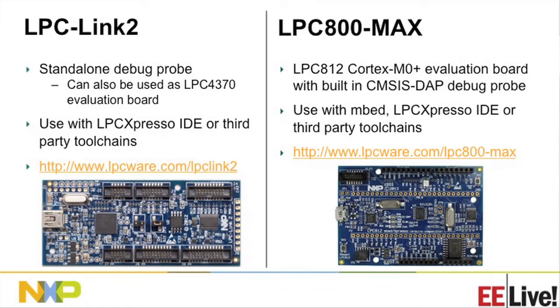I just want to mention a couple of other boards that you may come across. I mentioned that the LPCXpresso version 2 board has this LPC-Link2 implemented in it. We actually have a standalone version of that debug probe as well. Same basic functionality, works the same way, downloads firmware exactly the same, but it's a little standalone board. And this can also act as a simple evaluation platform for NXP's LPC4370 family, which are a triple core design. So they've got a Cortex-M4 and 2 Cortex-M0s in them as well. And again, more information on those on that link there.